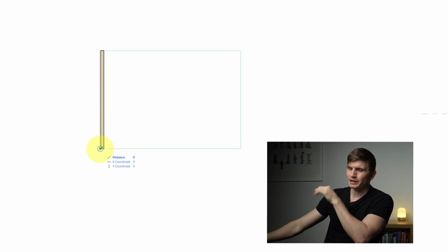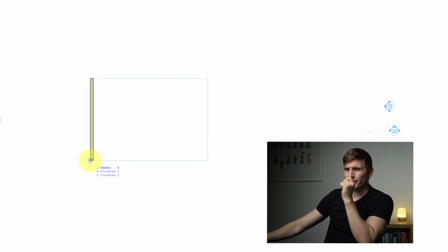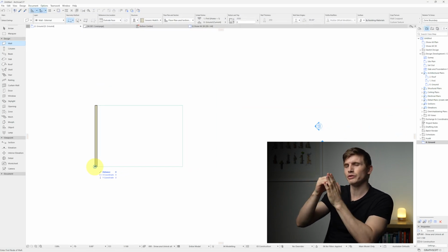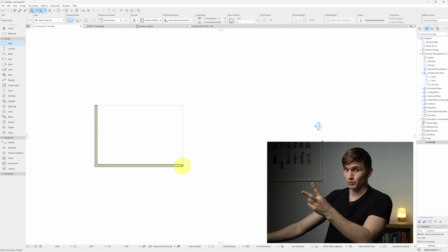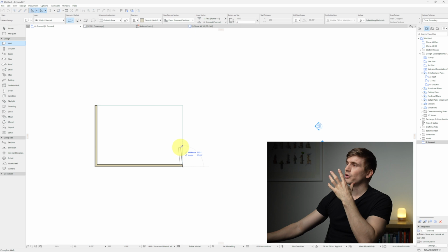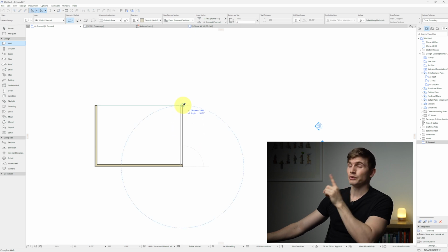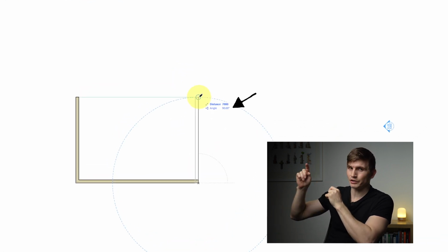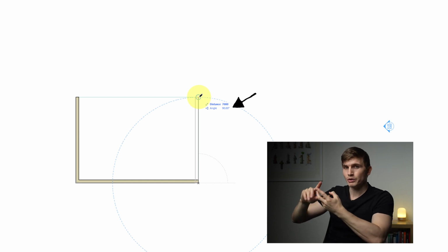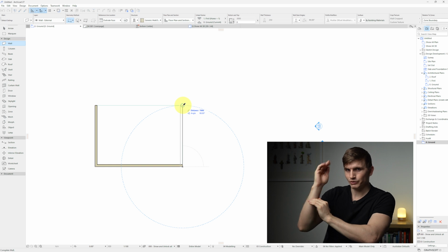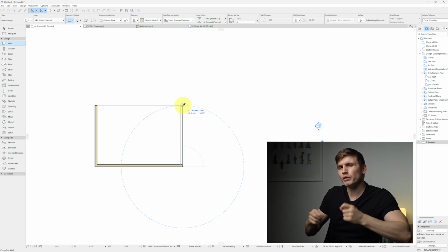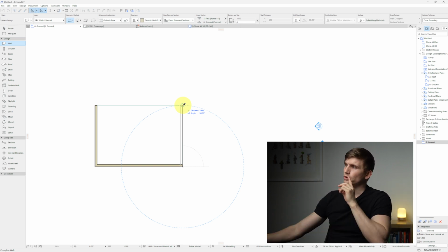Once we see this little tick in the bottom left-hand corner, we'll know that we're right on that node that we need to click so that the wall is directly over that slab. So we'll click and drag it on across until we see the pencil turn black, and we'll click once more. We've got our second wall in. Let's repeat that process all the way up until it hits to the top. And you'll see just underneath, it mentions that it's at 90 degrees. We always want to be drawing at 0, 90 degrees, or 180 degrees, just so that we're always straight with our walls when we're drawing simple structures, so that all the measurements are accurate that we're going to add in later. We'll click once more.